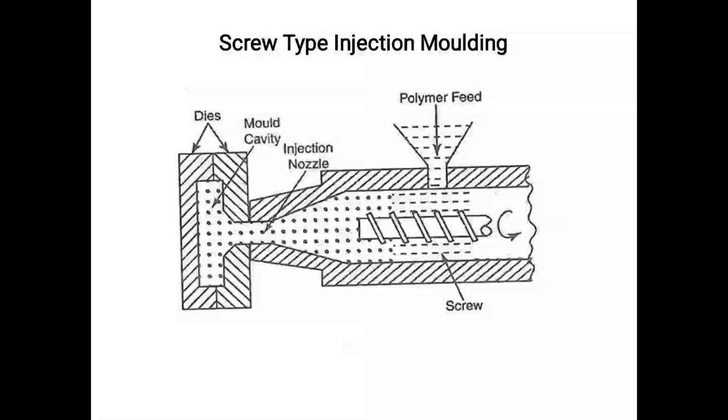The jet molding process is used to solve the problems occurring in the injection molding process. Reaction molding is a recent development in injection molding. In reaction molding, low viscosity monomers are used in the mold. A chemical reaction takes place between resins at low temperature and a polymer is created. In jet molding, the plastic is preheated to about 93 degrees centigrade in the cylinder surrounding the nozzle. Reaction molding is suitable for the production of polyurethane moldings. The injection capacity of injection molding machines ranges from 12,000 mm cube to 2.2 into 10 power of 6 mm cube.